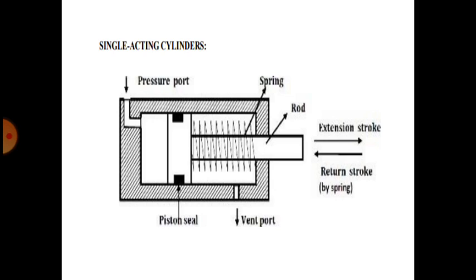In operation, the fluid is let in through the inlet port at the cylinder end as the pressure is built up in the cylinder. A force is exerted on the piston. Force is the pressure of the oil times the area of the piston, so the pressure is converted into force. This force exerted on the piston in turn causes the linear motion of the piston.